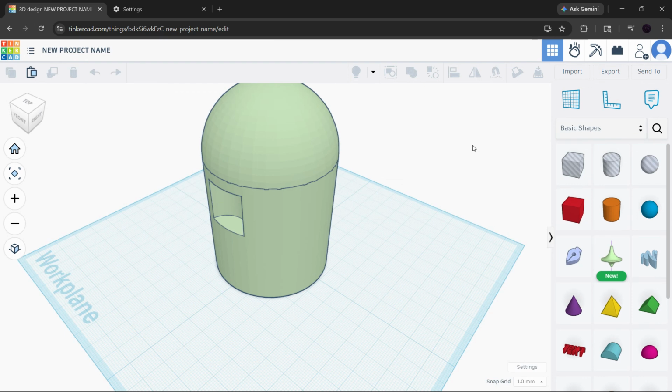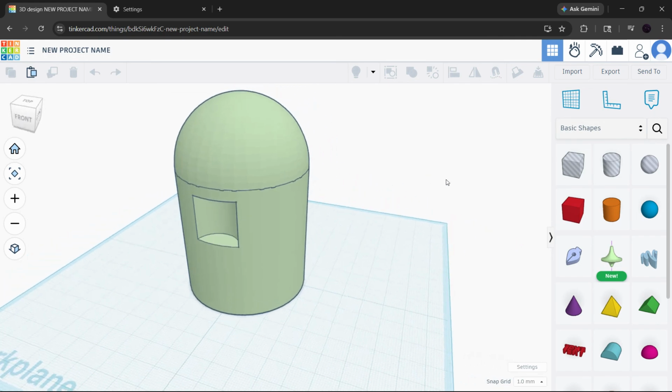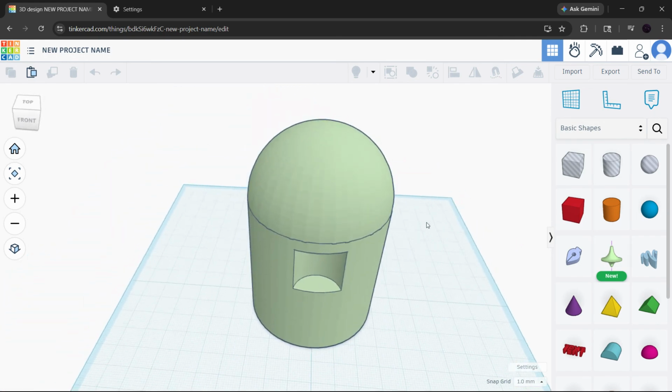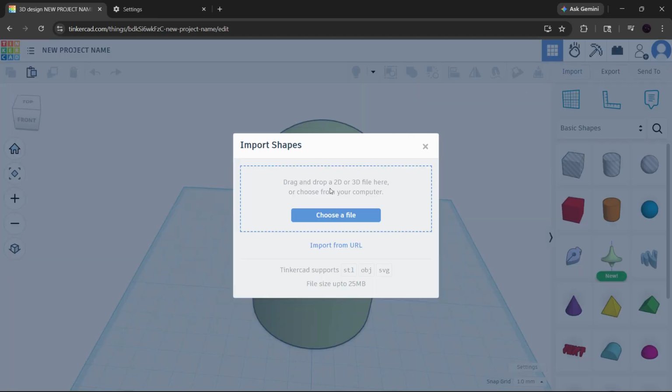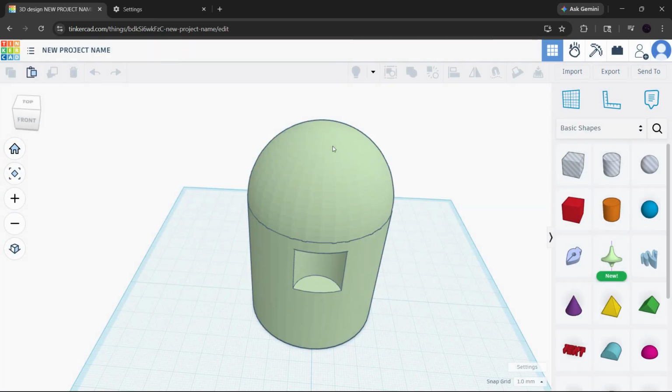So to quickly recap, if Tinkercad gives you an STL import error, first check the file size, triangle count, and scale. Then repair the mesh in MeshMixer or simplify it in Blender. After that, make sure browser hardware acceleration is enabled, try a private window, and if needed, re-export the file as a binary STL. Most import problems can be solved with one of these steps.